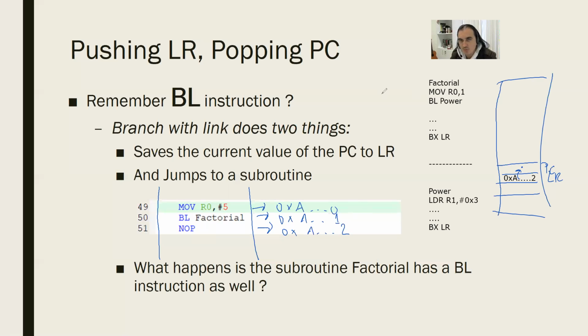So in the instruction memory, for example, let's say 0B something something 1, 0B something something 2, and 0B something something 3. There are the lines of code here. When you call BL, it will do the exact same thing. It will change the program counter so that it will execute these lines of code, and it will change the value of LR to this next line.